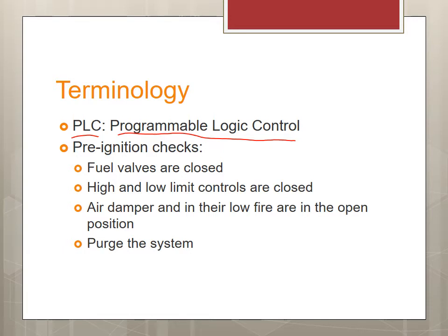It does a pre-ignition check. Before we turn on the boiler, we always have to do a pre-check. First of all, it will check that all the valves are in the closed and ready position. It will check the high limit and that they are closed and the circuit is made, and also check the airflow, I mean the air damper, and make sure that it is in the open position.